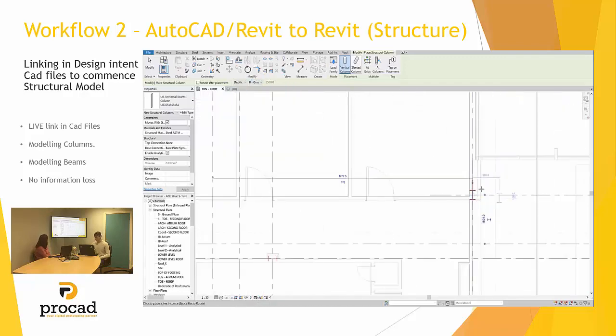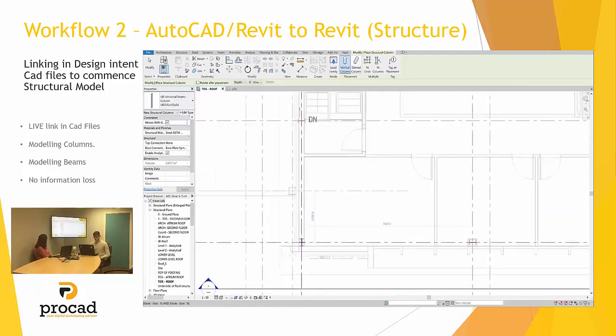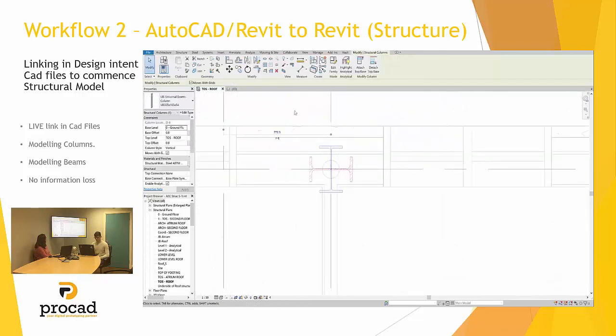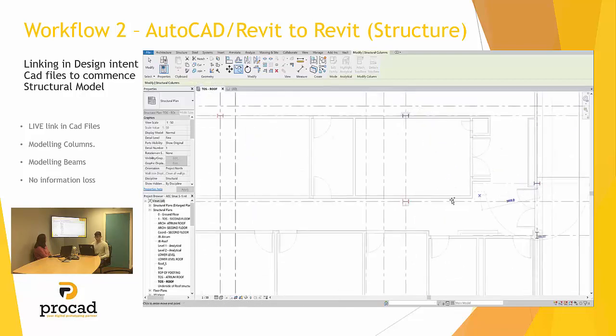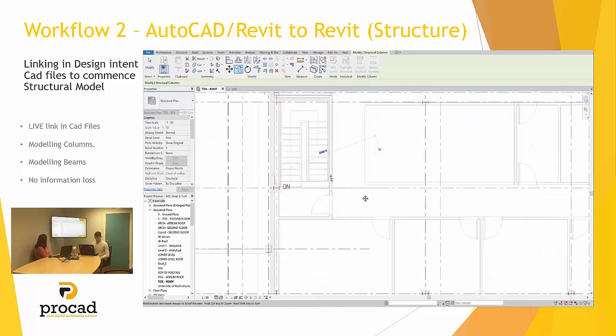So going in and placing the columns, you can see you can set the level where you want them, the base level, which is a ground floor, and using the grid system from both the structural and the architectural model, you can easily place each of the columns. If they're placed in the wrong position or they need to be rotated, it's very easy just going up to the modify panel and selecting those and rotating them.